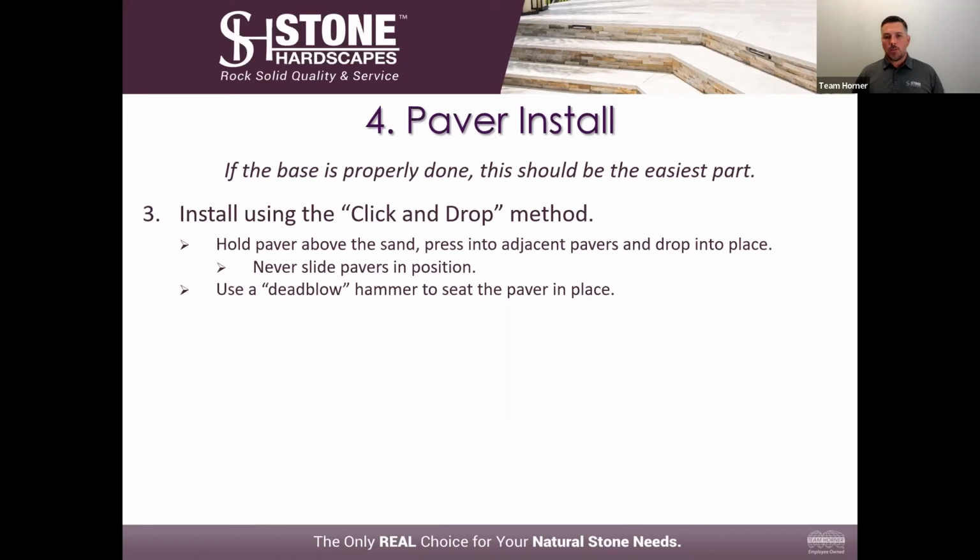You cannot use a mallet or a metal hammer because the vibration from that tool could crack the paver itself. A dead blow hammer eliminates the vibration and gives you the ability to use it to install the paver itself.